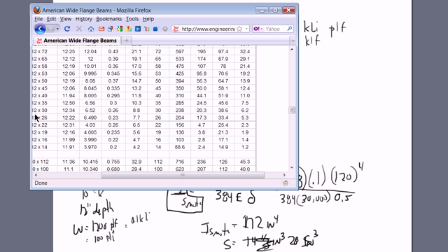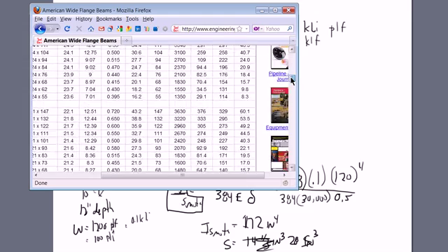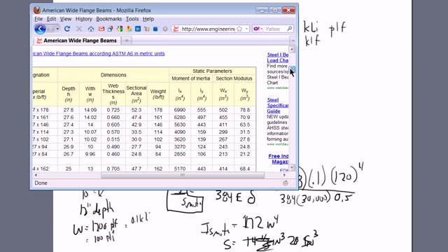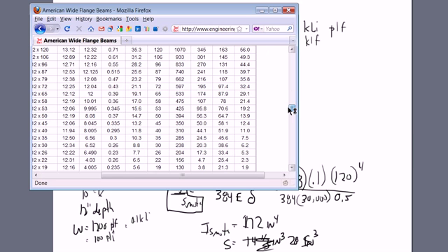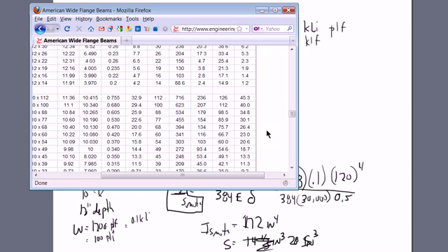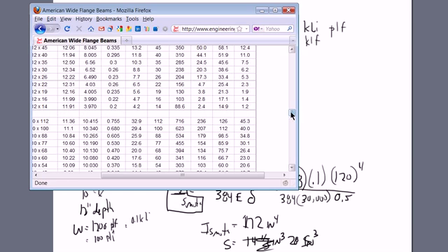And what you then want to do is you want to make sure that you highlight and grab all of the information, including the section modulus, the radius of gyration in both directions, the moment of inertia. And so this is not the best table, but in this case you can see you're going to design a W or select a W12 by 26, and that's going to help you then finally determine your stress as well, which we'll deal in a different video, or at least discuss about it. What you want to do is we won't put it in a different video, we'll put it here. So you have now, you're going to select a W12 by 26 with a section modulus of 33.